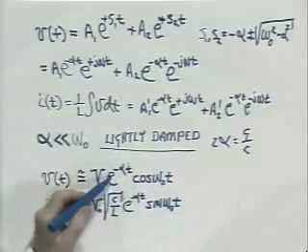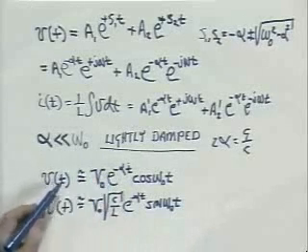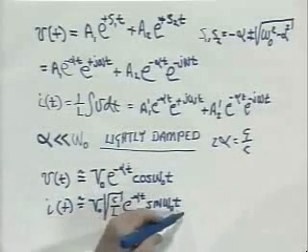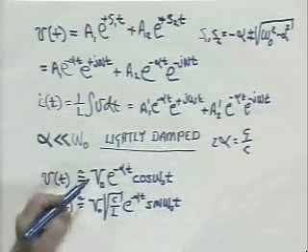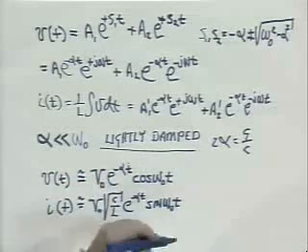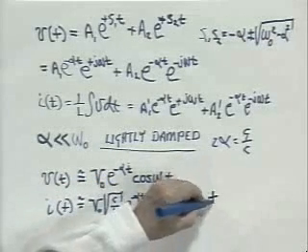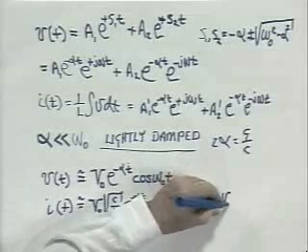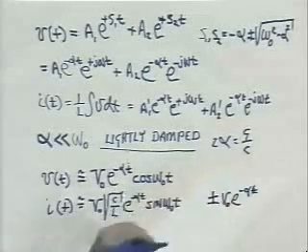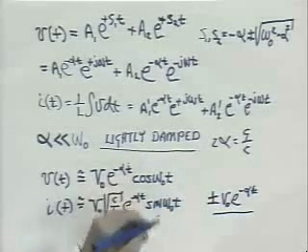So it starts out at value 1 for t equal to 0, and the initial voltage is just V0, which is correct. The initial current is 0 because the sine is 0 at t equals 0. But as time goes on, this cuts down both the sine and the cosine. So the function plus or minus V0 e to the minus alpha t creates, in effect, an envelope on the cosine and sine.